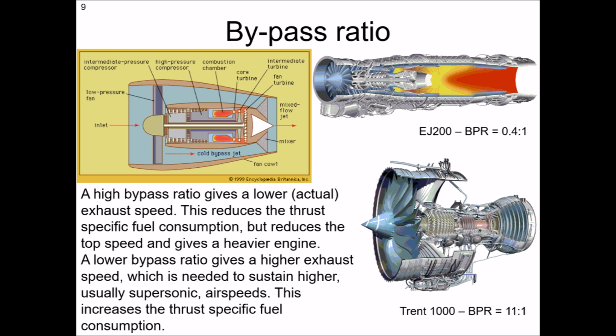And we also have something called turboprop engines, which are essentially gas turbines with old-fashioned propellers on the front of them, and they're similar to these high bypass ratio civil engines. But what I'm trying to show you in this example is that some of the air doesn't go through the combustion chamber. It's actually being driven by the fans, which is giving thrust, but cold thrust, if you like. And that's the difference between the two engines.